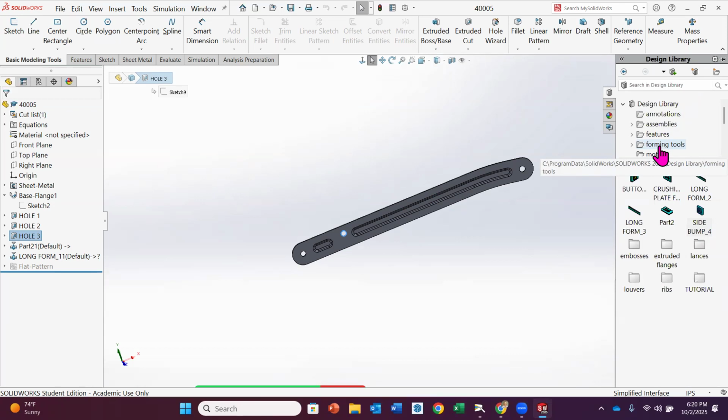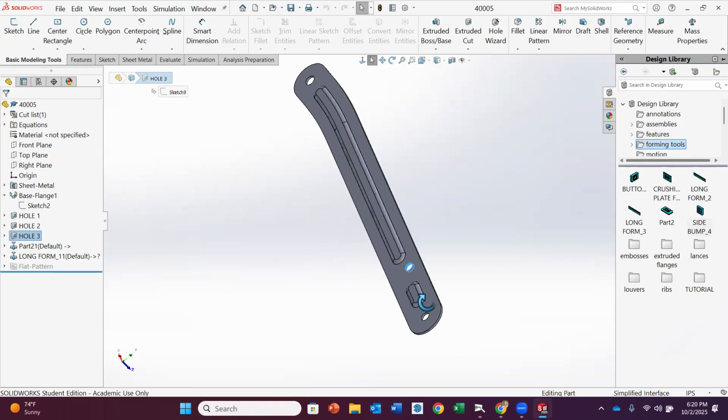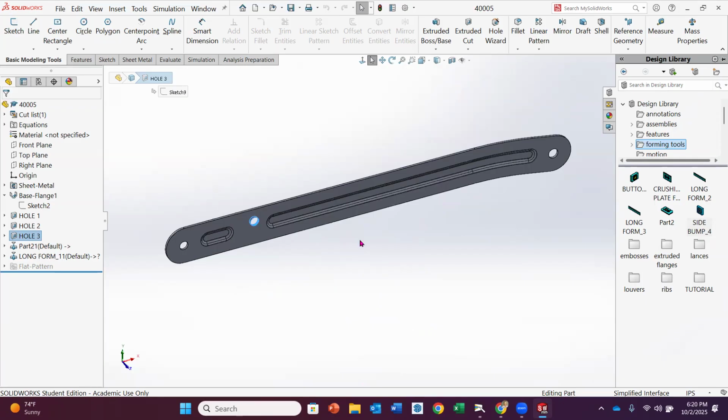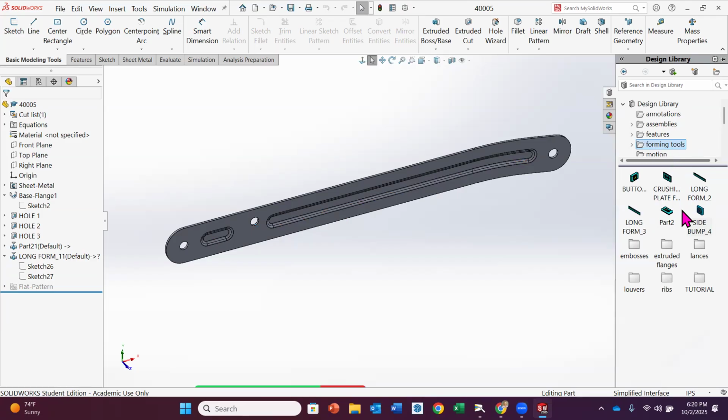If you don't, it doesn't always recognize it as a form tool. I learned that too. You'll notice on this part, I have these two bump outs on those handles. Remember, this is a left and a right. So when I have my form tool here, I'm going to open it through here.